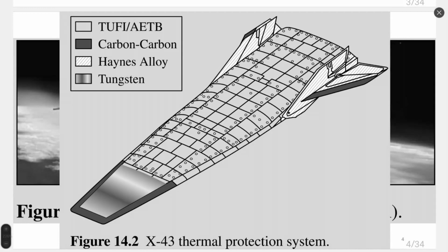Hypersonic velocity, where Mach number is high, Mach more than or equal to 5, is characterized by extremely high temperature on the surface because of friction and because shock waves create elevated temperature. Transformation of kinetic energy to thermal energy happens mostly on the surface of these flight vehicles.